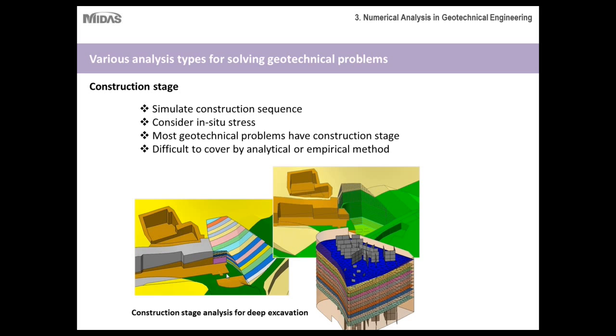As you can see, even in the excavation itself, the layers were separated, and then later on during the construction of the basement foundation, the piles were separated. The basement layers were separated into different stages. So later on, when the analysis is complete, you can combine all of these stages to get a really detailed understanding of the effects of the excavation and the construction on your foundation and the adjacent structures.